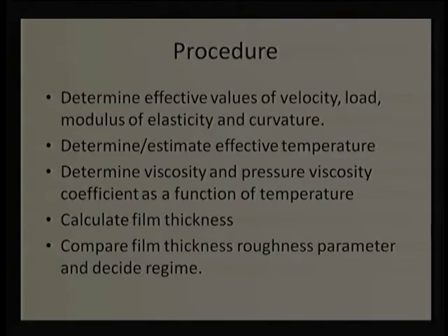Then the next step is to determine and estimate the effective temperature. We have not introduced any temperature relation. We need to go for the thermal balance, thermal equilibrium, to find out what the effective temperature will be. Then once we know the temperature, we should determine the viscosity. As we know, viscosity is affected by temperature. The higher the temperature, the lesser the viscosity.